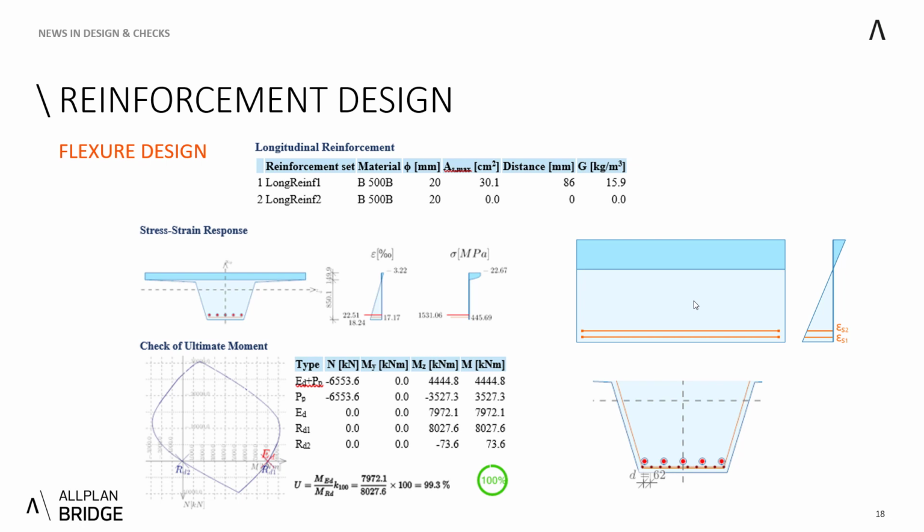And in this case, we have designed 30.1 centimeters squared, and at the bottom of this picture, you can see that the designed area corresponds to several bars, which have a clear spacing between them of 62 millimeters, and we have plenty of space left if we need it. So we didn't really need the second layer, which we might end up needing in case of reinforced concrete sections.